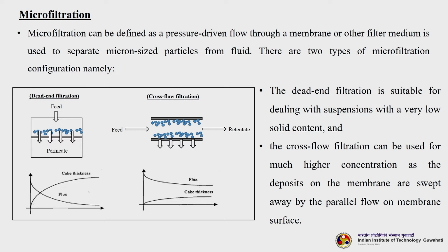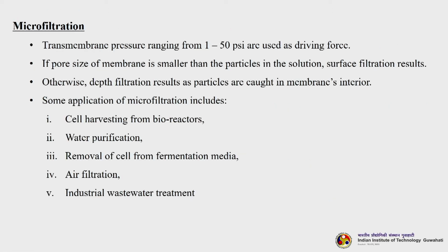So, very highly concentrated solvents or mixtures can be processed through cross flow filtration, since the depositions of the solutes on the surface of the membrane are usually swept away by the parallel flow on the membrane surface. The transmembrane pressure for microfiltration is usually 1 to 50 psi.